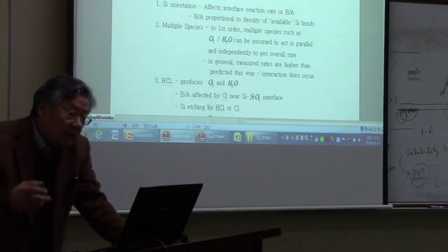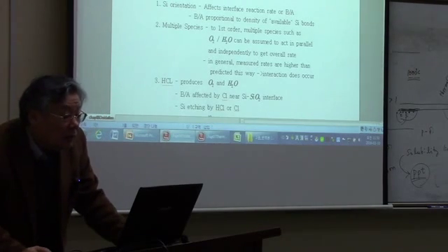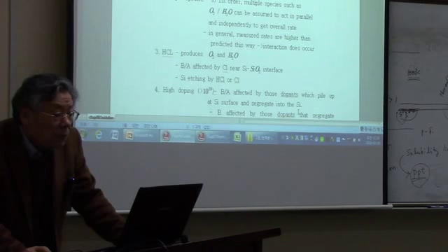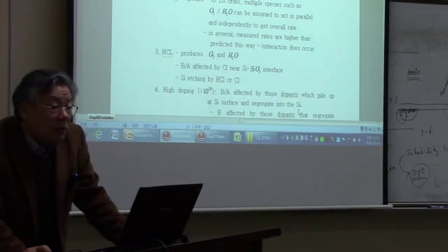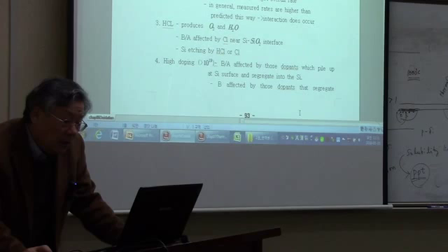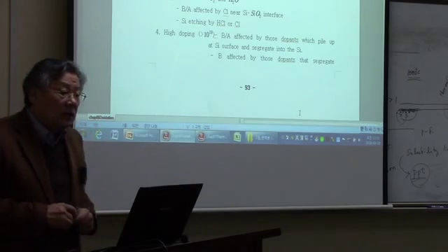So that is the hypothesis, a speculation that we can see. But in real practice, okay, the HCl oxidation really happens in the industries. Well, here's a summary. Silicon orientation affects the B over A, not B. And if you have multiple steps, then you know how to calculate the final thickness after the multiple processes. HCl is what really happens in the industry, and the doping will affect the B over A to enhance the oxidation rate.